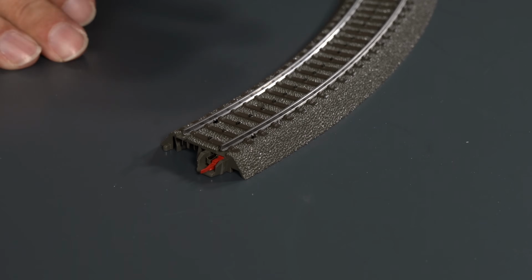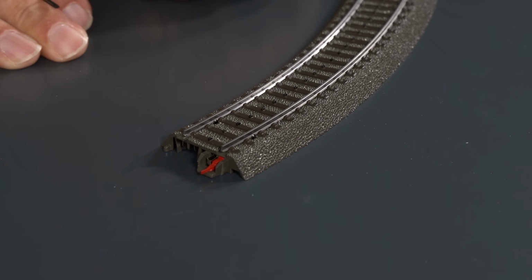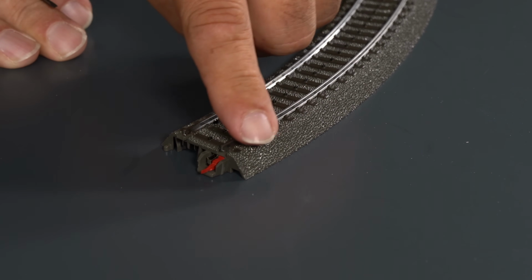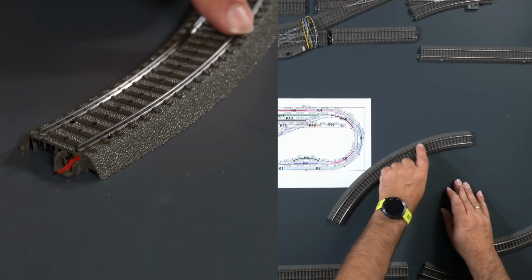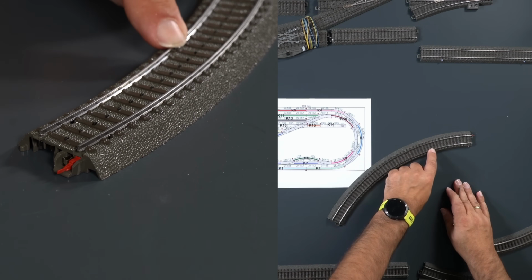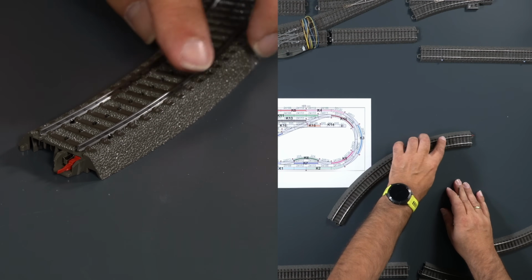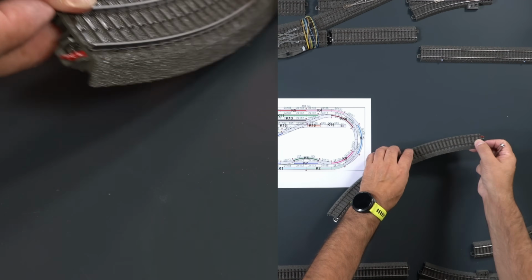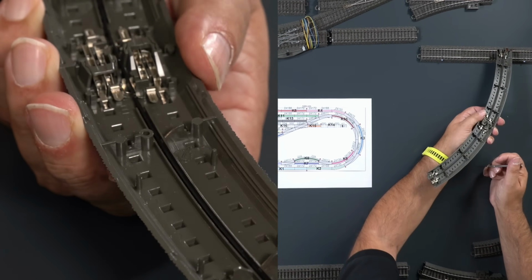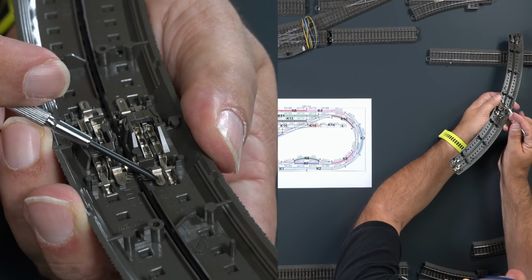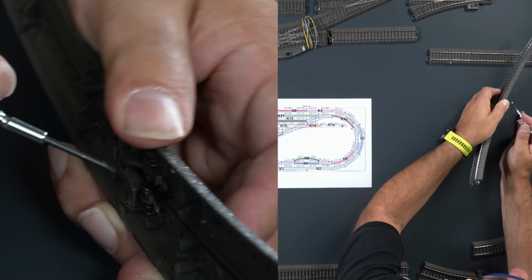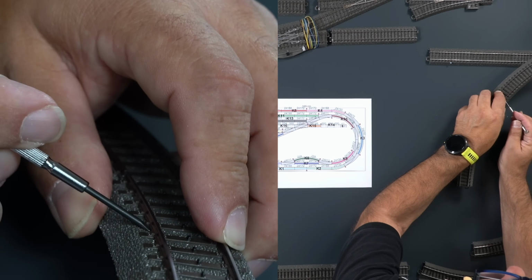Done. Now it's important to later solder the cable for the feedback module onto the correct side. Of course, I've made the separation here, which means the gray cable for the feedback module needs to go on this track, not on that side. So I always put my finger on this side and then turn the track over. That way I also have a marker at the same time and know, okay, if I were to solder the wires for the feedback module here, then I turn the track over and realize, oh, that's wrong.